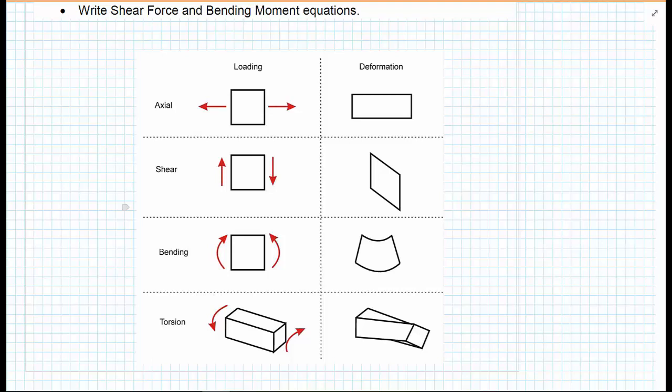So where we have a piece of material here, and we've subjected this material to two forces pulling on that piece of material, as a result of that pulling, the piece of material stretches, so the original shape would have been something like this, and it will also, due to something called Poisson's ratio, which we'll discuss in strength of materials, have got thinner as a result. That's true for most materials, but not all.